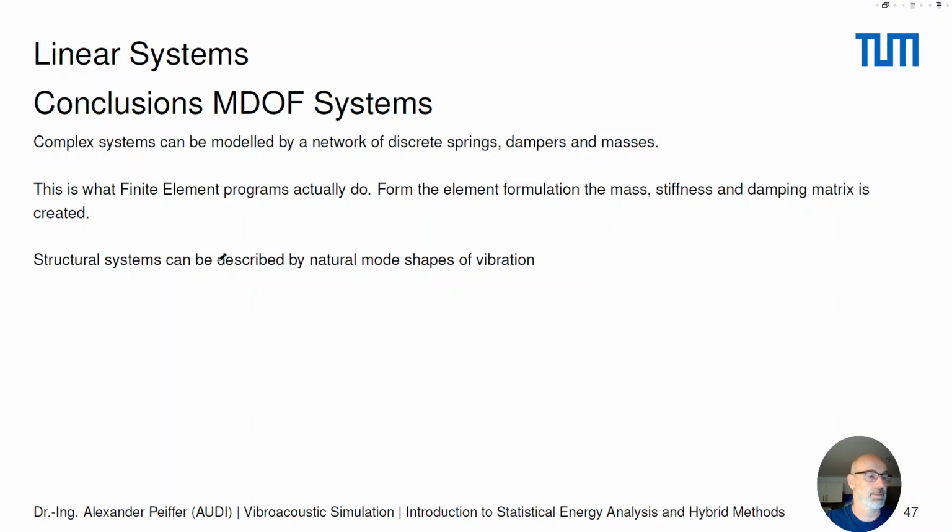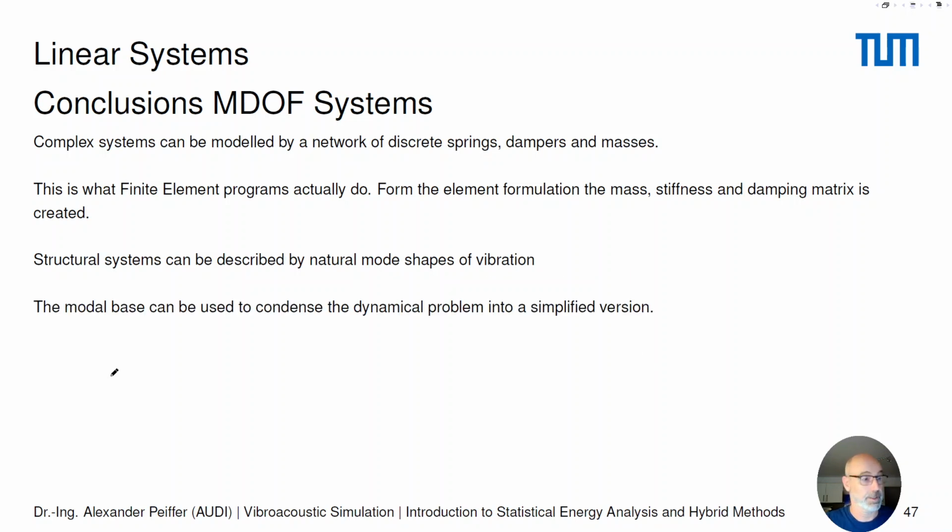A structural system can be described by natural mode shapes of vibration. And this modal base can be used to condense the dynamical problem into a simplified version. So this is something to simplify our problem, also in terms of numerics. Once you have the modes, the calculation times of all responses are definitely much faster.